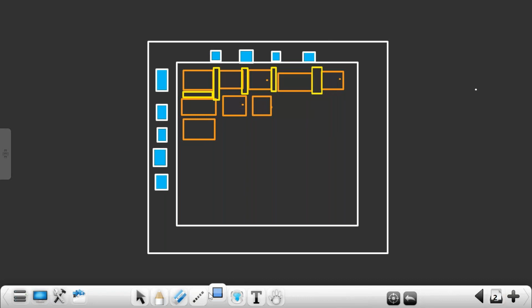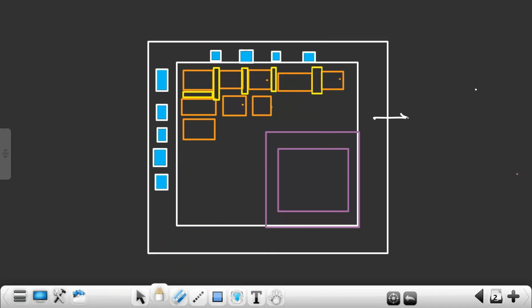If it is a multi-voltage design, then create the voltage area also. So this floor plan, you create a DEF, design exchange format, and this DEF you forward to the physical aware synthesis tool.